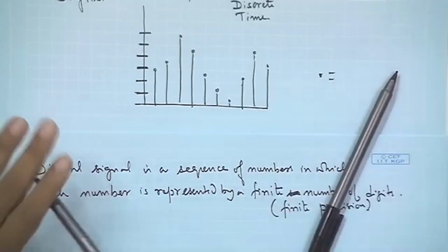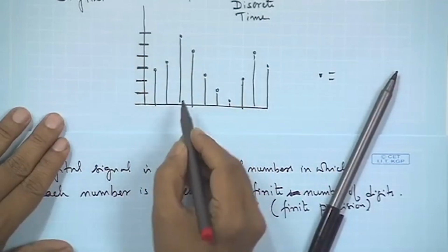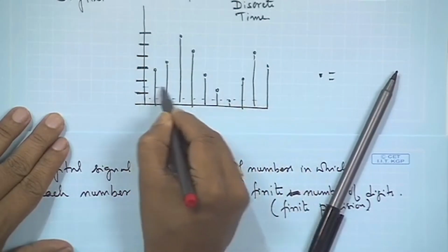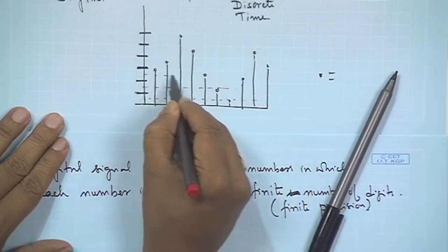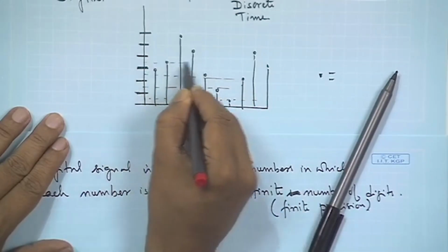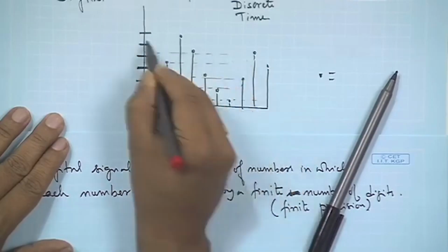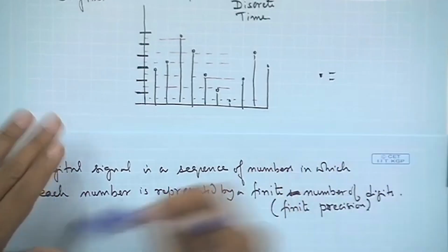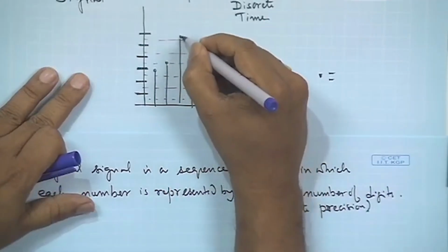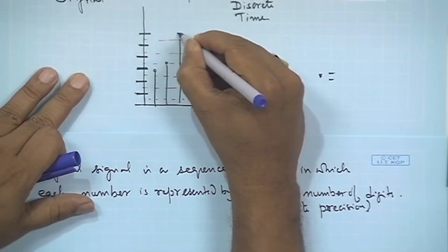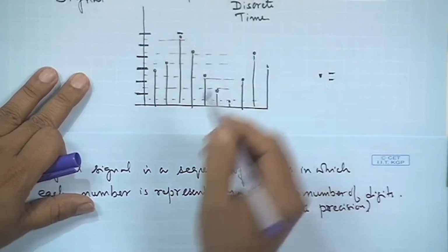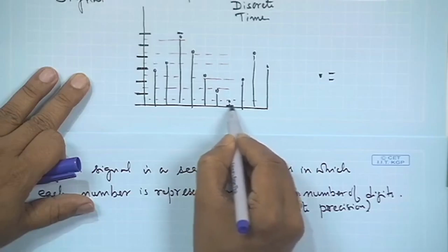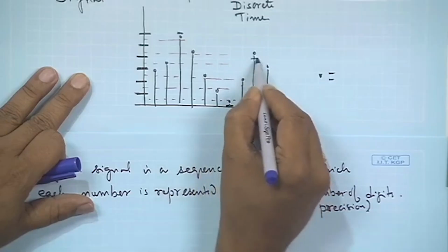Suppose one has decided these intervals, one can find the middle point of each of these intervals, and if the signal has gone above the midpoint, then it would refer to the higher end of that interval, and if the signal has remained below the threshold, it would refer it to the lower point.